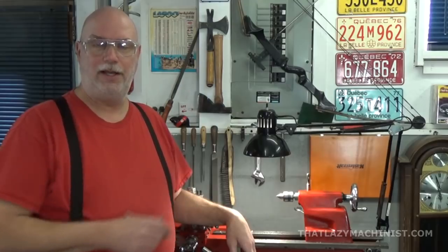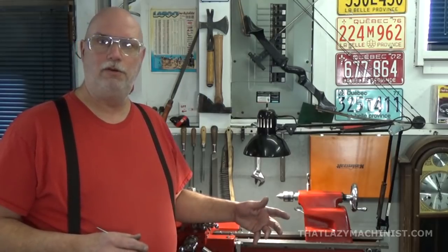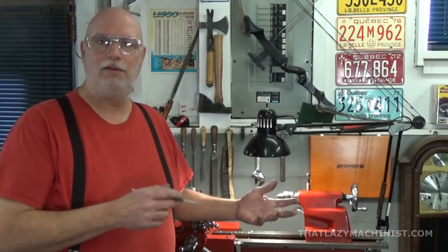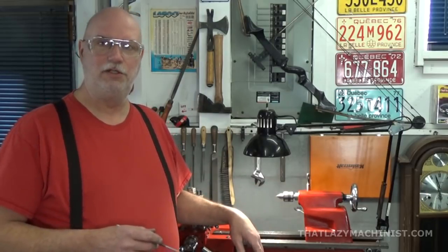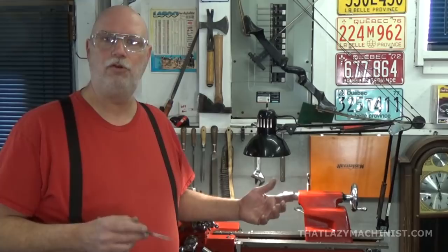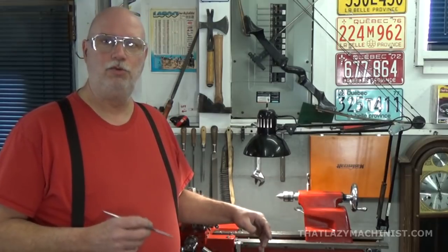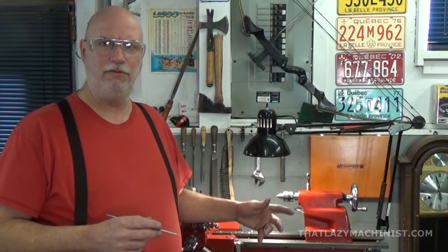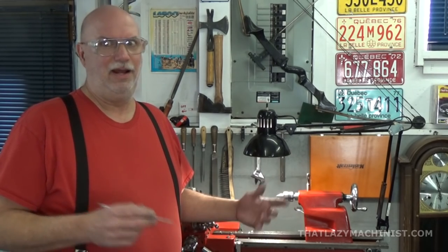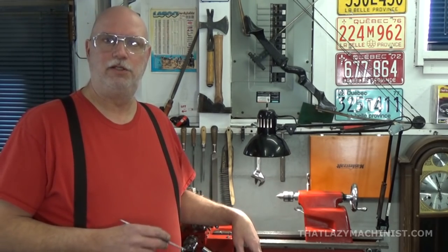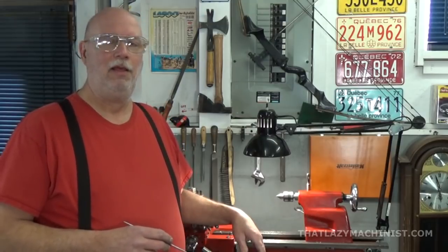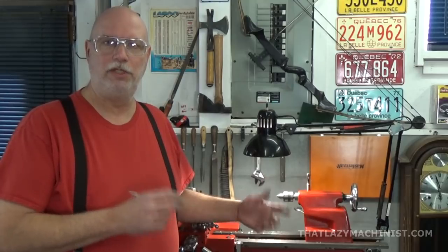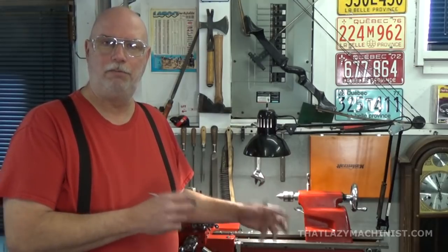Knowing that the largest diameter I'm going to turn here is 200/1000ths of an inch, it may seem excessive to start with a 500/1000ths of an inch part. I mean, that's 300 too much. But there's 2 reasons why I'm starting with that 1/2 inch part. The first, well, is that I had a piece of 1/2 inch stock kicking around. And the second, well, is that I want to maintain a maximum of rigidity throughout the machining process.